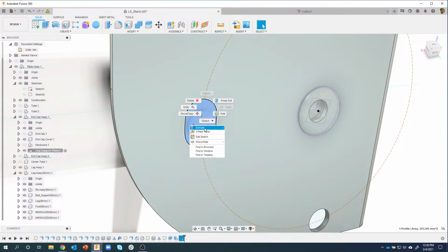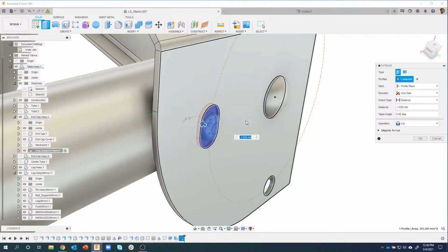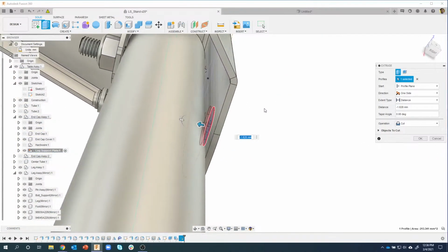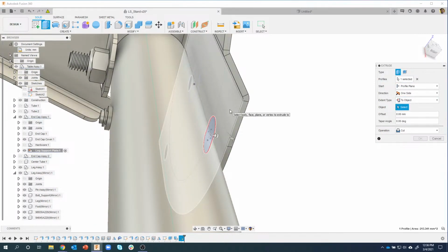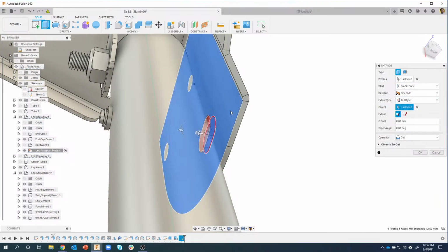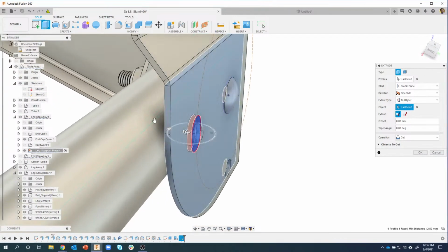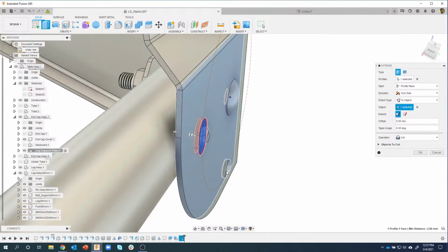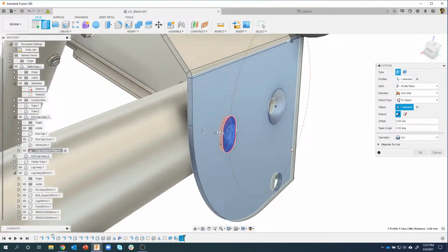Let's go ahead and extrude this guy. I like to start to drag. Well, I want to go a very specific distance. So instead of distance, I'm going to say go to this face, and you're going to see that it's going to extrude the correct distance to whatever the thickness of that face was. So instead of me guessing, I said go exactly to that wall right there.